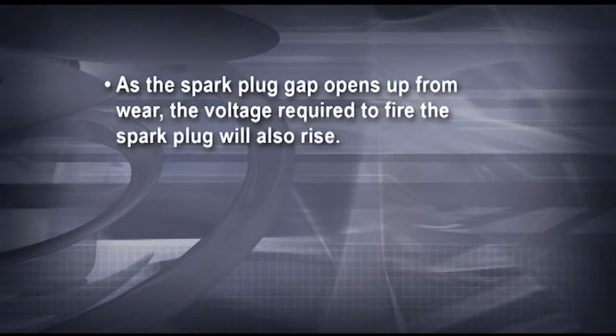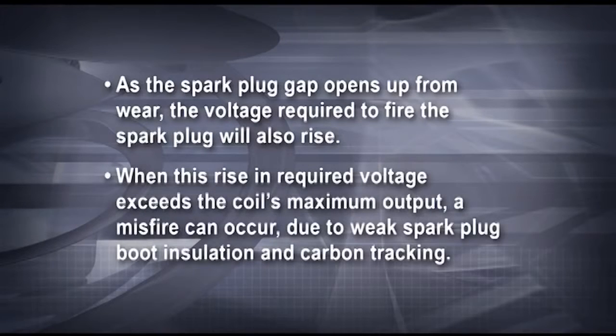You have to remember, as the spark plug gap opens up from wear, the voltage required to fire the spark plug will also rise. When this rise in required voltage exceeds the coil's maximum output, a misfire can occur. The misfire could be related to weak spark plug boot insulation and carbon tracking. A lean injector can cause secondary voltage demand decline and can lead to breakdown of the insulation and secondary components.